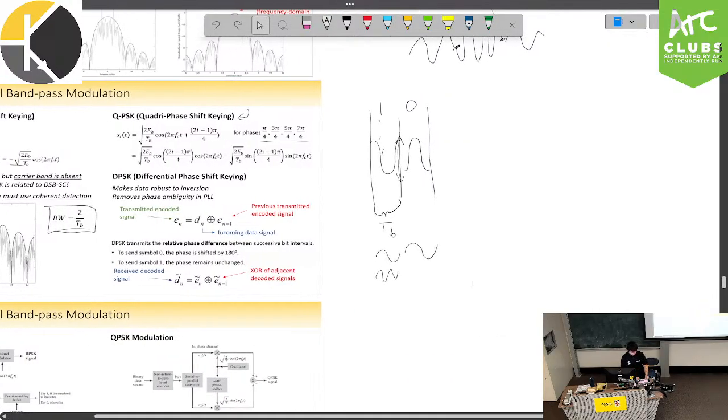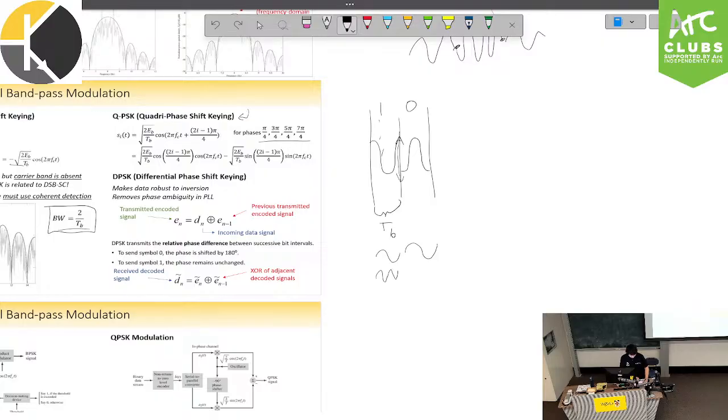So from 0 here to 1 on TB, this is where all the action happens, but on your frequency diagram, you have -1 on TB here, everything gets modulated, so then you end up with your 2 pulses out here, so you get a bandwidth of 2 on TB.